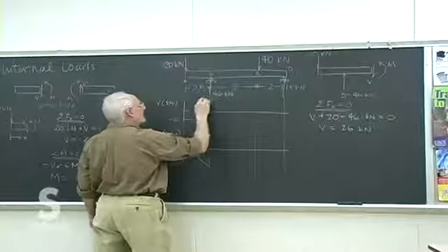And then we can draw our shear moment diagrams. And we can speed it up a little bit if we remember some of our graphical relations between these. I happen to know offhand that we only have negative shear on this one, so I'll go ahead and draw the axes like that.